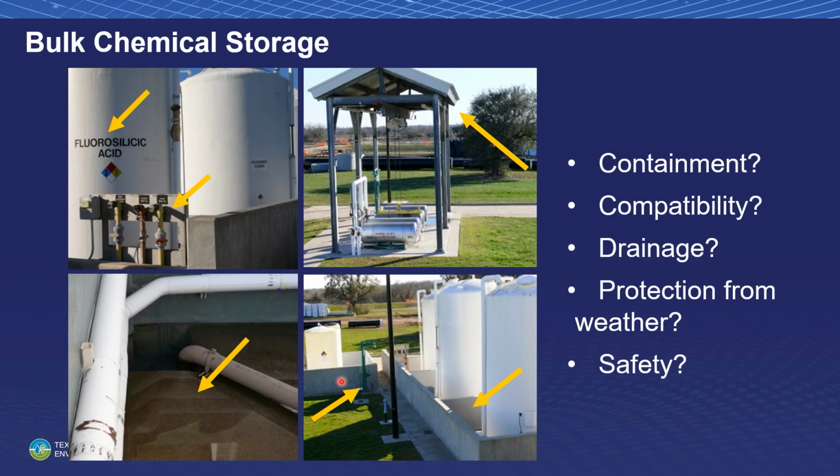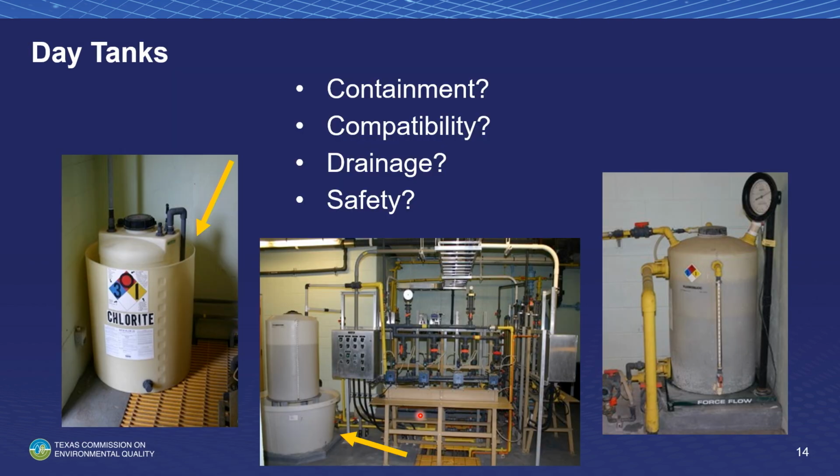And if you're gonna have the pumps to pump the rainwater that collects in that containment structure out, be sure that it's going somewhere other than just general sanitary sewer. Make sure you can neutralize the waste before you send it off to the wastewater plant. Day tanks, the importance of day tanks, I don't want to overemphasize.